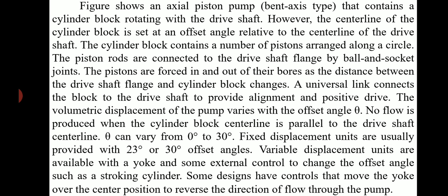Variable displacement units are available with a yoke and some external control to change the offset angle, such as a stroking cylinder. Some designs have controls that move the yoke over the center position to reverse the direction of flow through the pump.